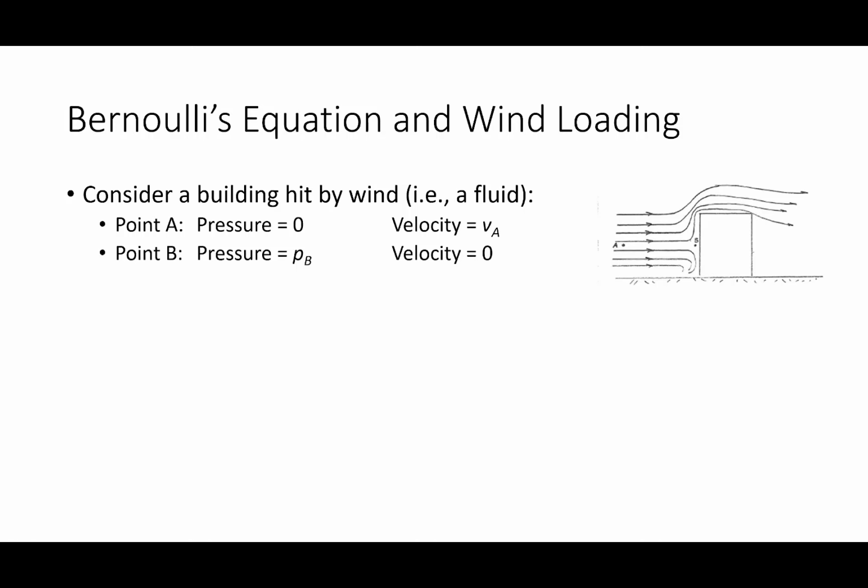And if you think about wind, how do you characterize wind? If I go on my iPhone right now and look up the weather for the given area, and I look up the wind, it's going to tell me the wind in miles per hour, right? So ultimately what I'd like to be able to do is take that wind speed in so many miles per hour and convert it to a pressure that's going to be applied to the building for the purposes of design. And this is really a Bernoulli's equation problem, at least fundamentally, okay?